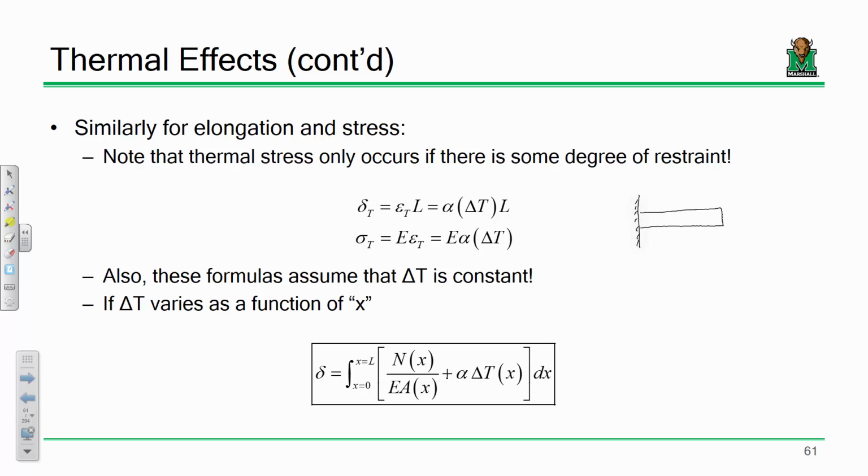Now, I propose that if you take that bar and you heat it up, what's it going to do? It's going to get longer, right? So it's going to freely get longer like this, okay? Now, let's say for the sake of discussion that's all I have. I propose the bar is going to freely deform and it's going to experience thermal strain but no thermal stress.